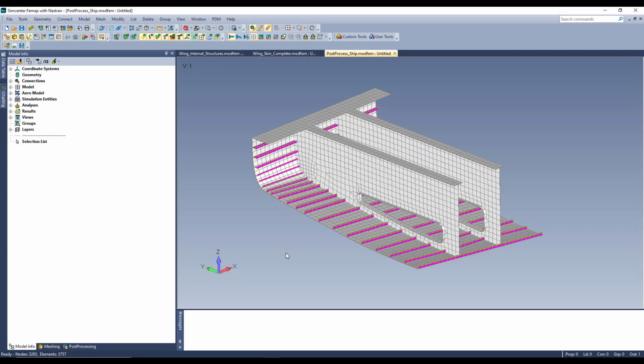In the second part of the meshing enhancements for Simcenter Femap version 2301, we're going to look at how we can use the mesh on mesh to edit a mesh with beam elements. And this edit will refine and unrefine the mesh with whatever size you want.